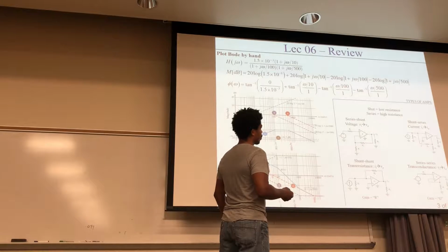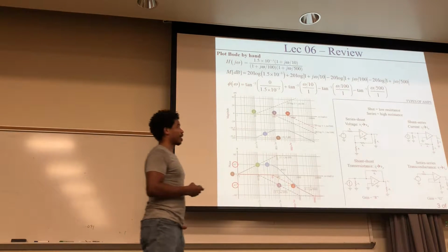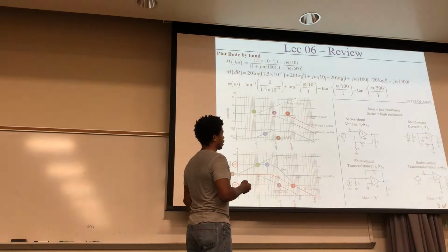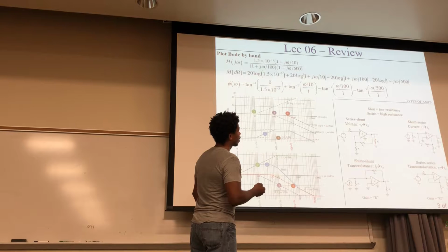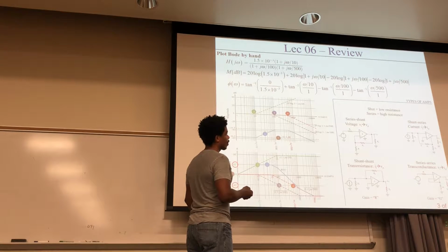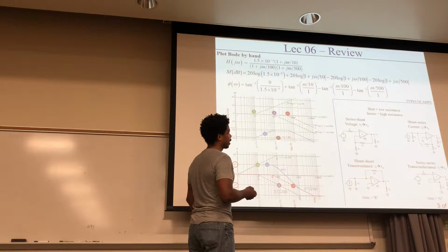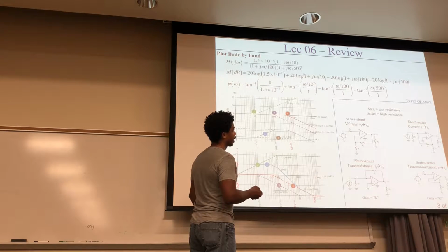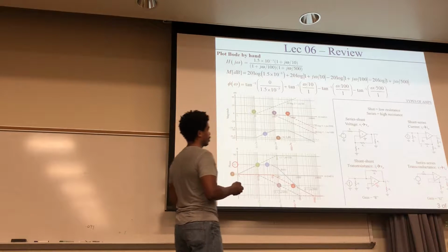And the reason that there's 4 types is because those are the 4 kind of combinations of amplification, right? So here you're just amplifying voltage from your input voltage to your output. Here you're going from a current input to a current output. But here you're going from a current input to a voltage output. And there you're going from a voltage input to a current output. Okay? So that's all the various possibilities.